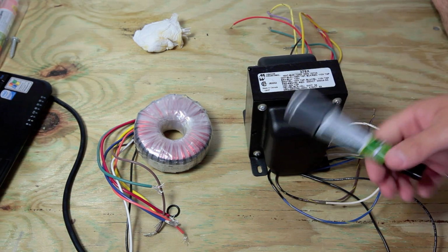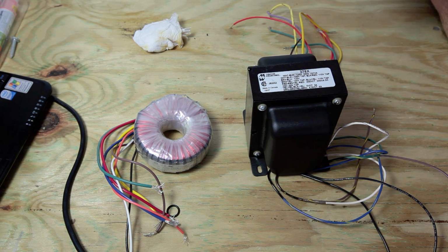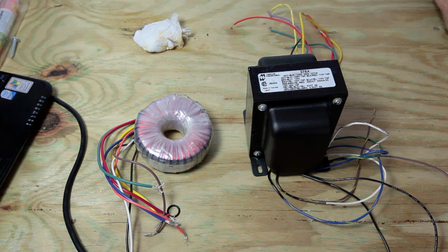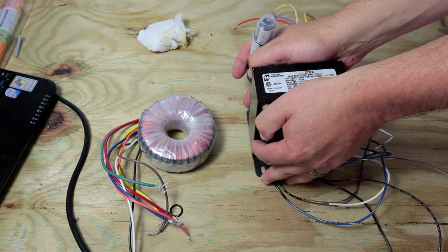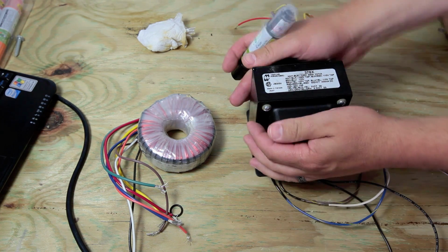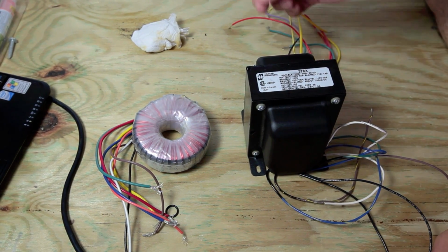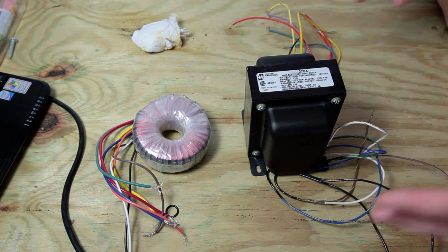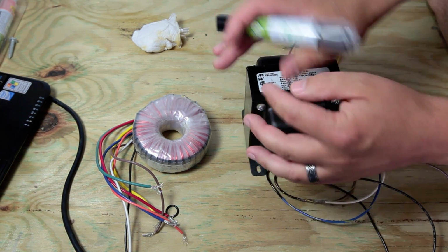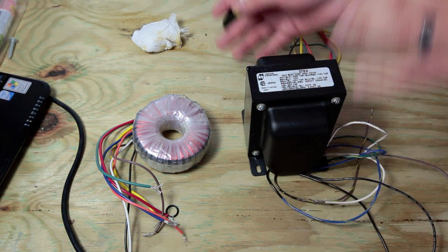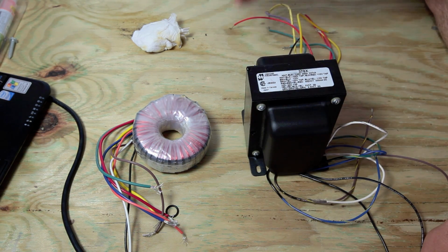first of all, you'll notice the cans. Remember I was talking about how you get flux leakage, right? And so they surround all the windings with a ferrous can. I'm pretty sure it's not iron. I don't know what it is, but it'll focus the magnetic flux enough that it really doesn't leak out of here, so it doesn't jack up the rest of your circuitry, okay?